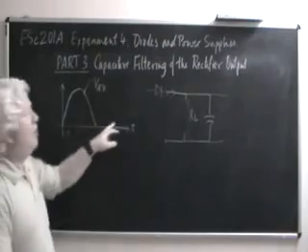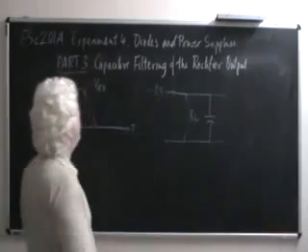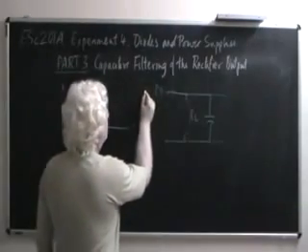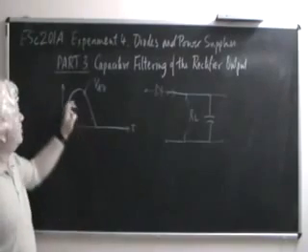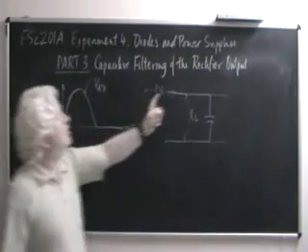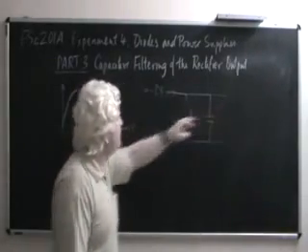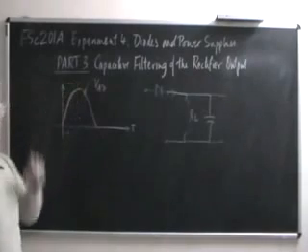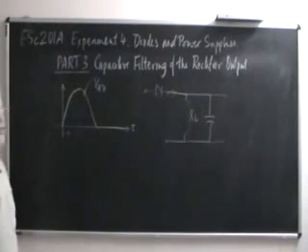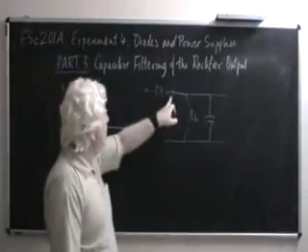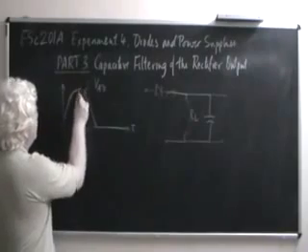But because of this capacitor, the diode is now faced with a falling voltage on the anode end, while on the cathode end the voltage is fixed at the peak value that it just crossed. In short, the diode stops conducting at this point itself.